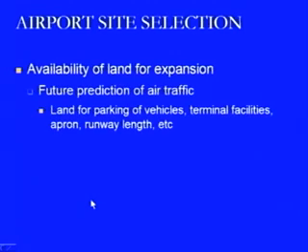Another factor is whether we have the land for expansion in future, because in future the traffic is going to increase, and when the traffic increases, we require space not only for the parking of vehicles, but for the terminal facilities, for the aprons where the aircraft will be parked, or the runway lengths on which the aircraft will be moving.